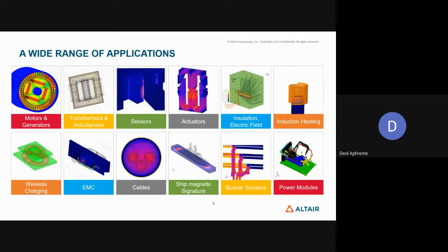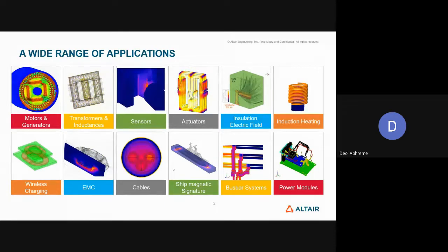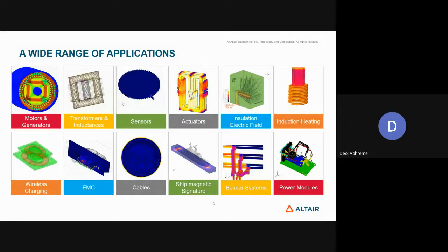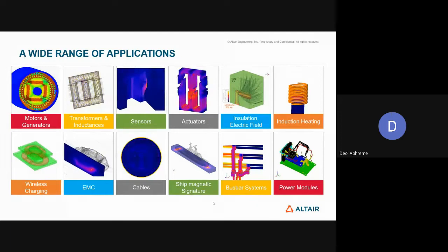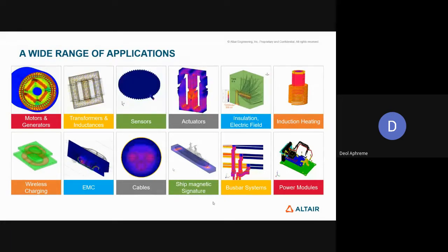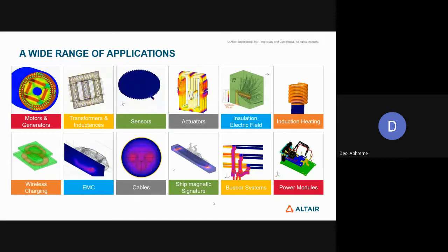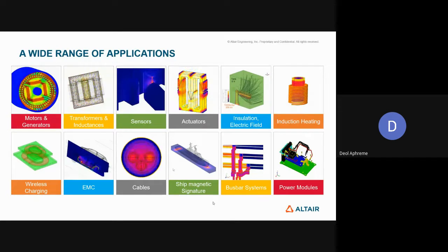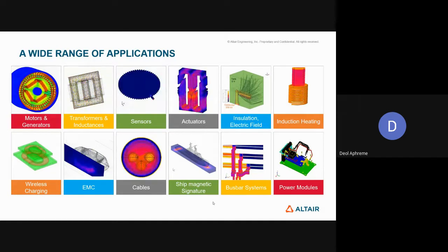Cables, maybe underwater, overhead, or buried, or any sort of cables, they need to be simulated and understood, so the coupling inductance, the influence of one cable on the other. In case there is an earth phase ground fault or a line to line fault, will the insulation break down? There are so many fault conditions and so many parameters that have to be understood of a cable.